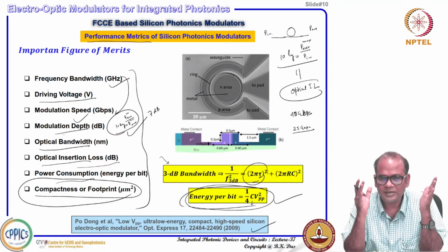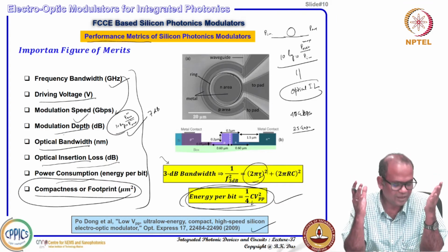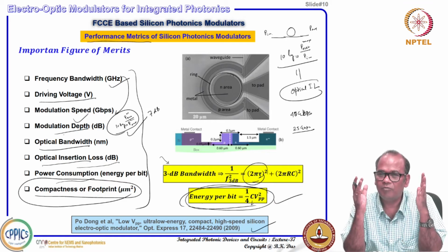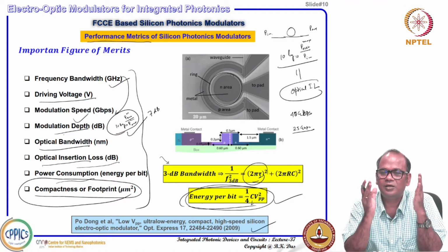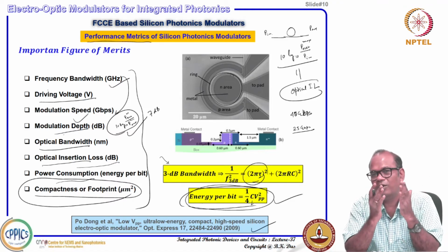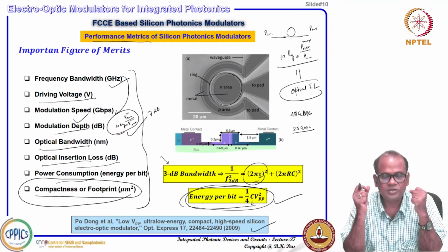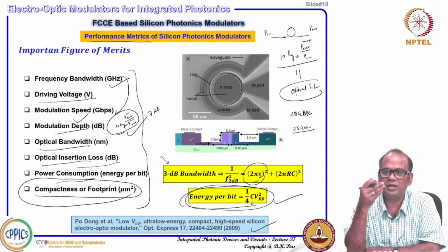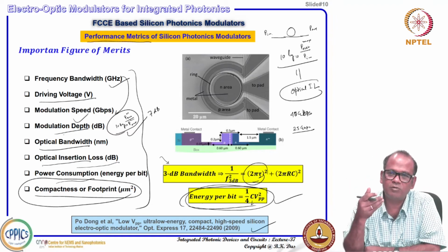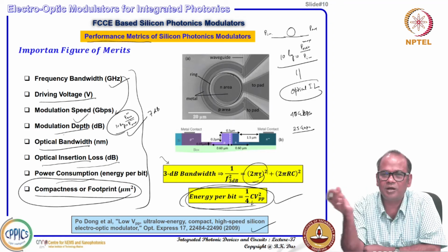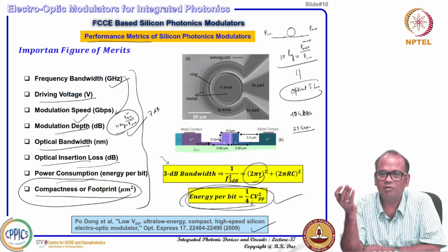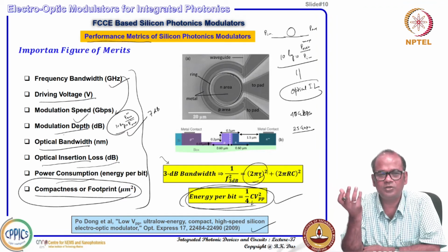So the present generation is going for micro ring resonators, where the footprint is small, though it is wavelength selective. But that is the future: you can multiplex more modulators and more ring resonators. Instead of millimeters of Mach-Zehnder interferometer length, you can have 10 microns of micro ring resonators, and you can integrate hundreds of them.